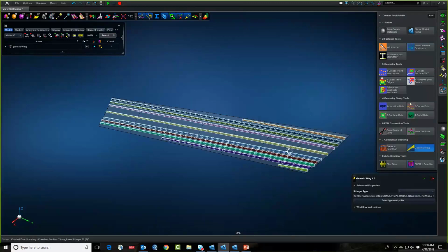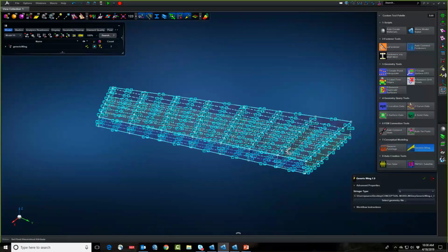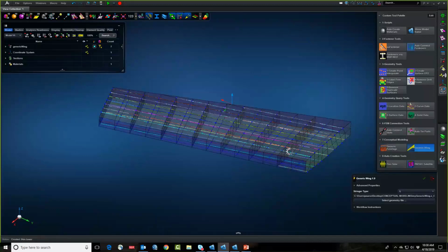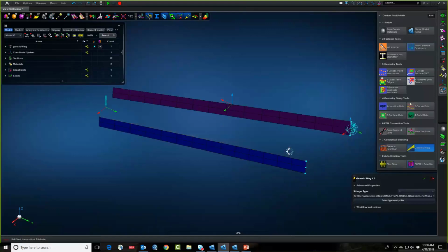Next, the script is taking all the pieces of the model and using the edge tie capability that I illustrated earlier to tie all the ribs and all the stringers, and you can see all the markers now for the ties. Now it's going through and identifying regions of the model, and in this case, it's applying the mesh control features that I want to get the mesh that I want in those areas. And the little scroll bar that's popping up now is me going back to each one of the areas and checking what the mesh is in that area, and making a decision. Maybe I want to update that mesh to improve it.